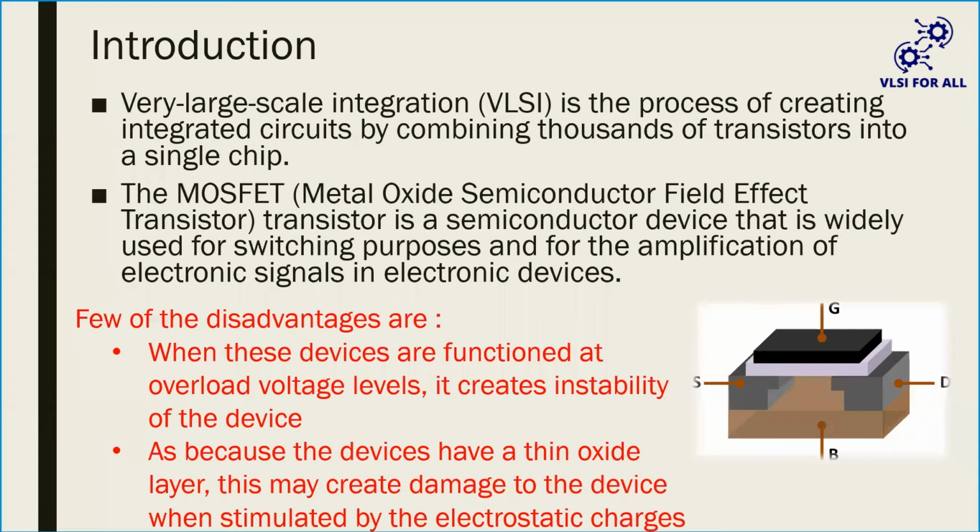That is the only reason BJT is not preferable in IC fabrication. Whereas FET and MOSFETs are symmetrical devices. Symmetrical in the sense that both source and drain are equally doped. That means you can use the drain as source and the source as drain. But in a BJT, the emitter is heavily doped and the collector is moderately doped. Hence, you cannot use the emitter as collector and the collector as emitter.